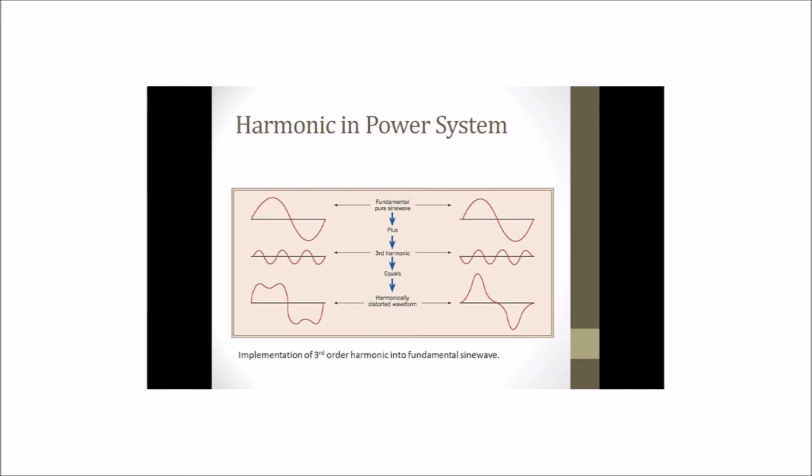In a deregulating power scenario, harmonic source detection assumes significance in an interconnected power system, as we all know. The presence of harmonic in an electrical system means that current and voltage are distorted and deviated from sinusoidal waveforms. Harmonic currents are caused by nonlinear loads connected to the distribution system, which is the result of nonlinear loads that convert AC line voltage to DC. That is what causes harmonics.